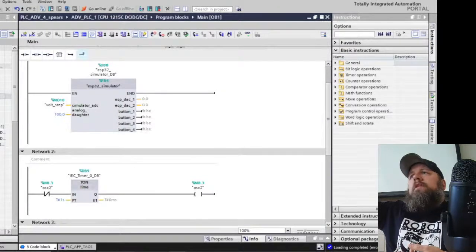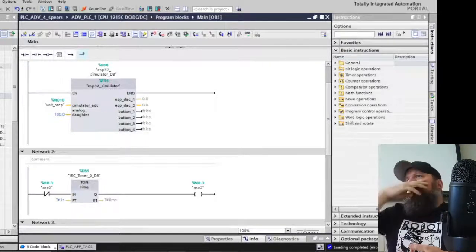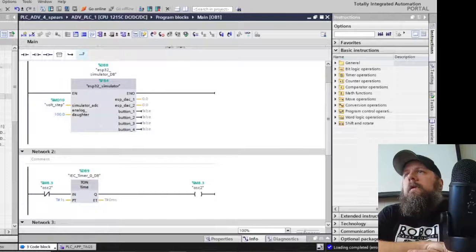Between those three things and a laser sensor down at the bottom, I can tell it to go this high, and then I could open up that baffle, and the feedback loop of the PLC would make the fan turn up higher, so that it would compensate for all the air getting lost out of that damper, right?